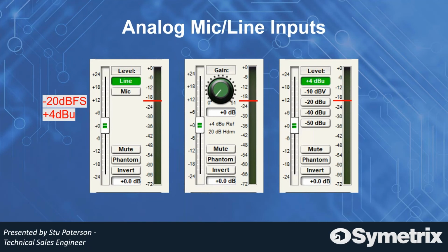If it's too high, we run the risk of going above 0. Well, there is no above 0. 0 is the ceiling on dBFS. You run out of 0s and 1s, which means it starts muting certain signals. So we have to balance those two together in order to get adequate gain structure throughout the remainder of Composer.